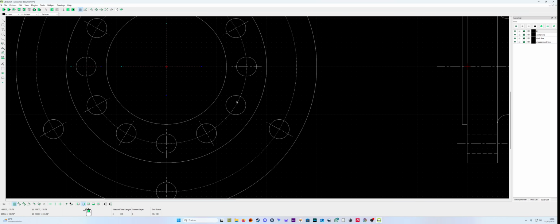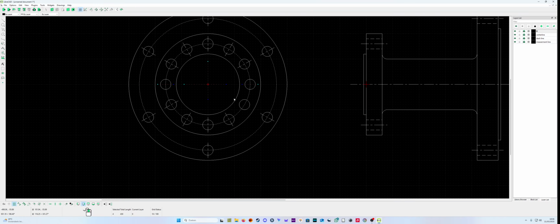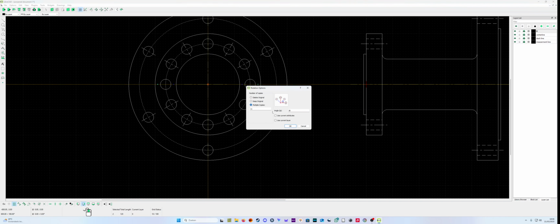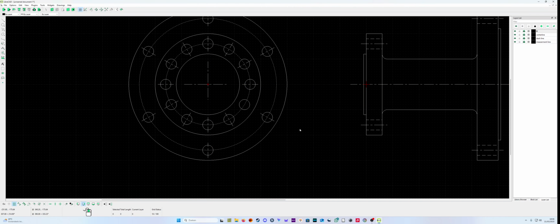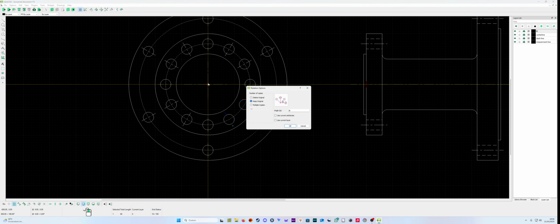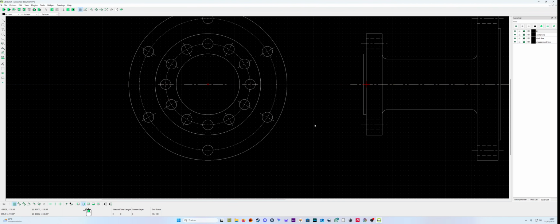So I'm missing a center line here. Yeah, that's also not good. So I'm gonna do it like this. I'm missing one center line. You see, guys, I'm missing one center line. So then I can say rotate. I can say like here, and I can say 30 degrees, and then I say keep original, do only one, and then it's going to the other side. Of course, I must take that one. You always see some things go wrong. So let's see, rotate is going here. All right, there it is.